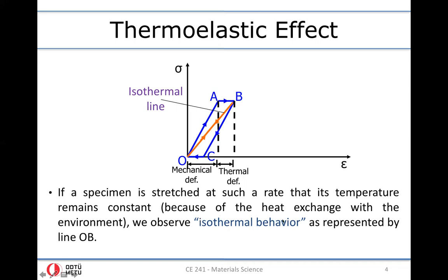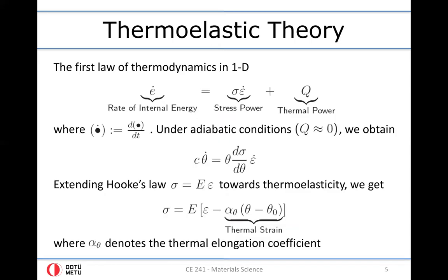This behavior is referred to as isothermal behavior, which corresponds to the response of the material under constant temperature, where we don't observe any temperature change because any heating that you would expect within the material will be dissipated to the environment. You deform the material so slowly that it will always have time to equilibrate thermally to achieve the environmental or ambient temperature. So this is what we observe.